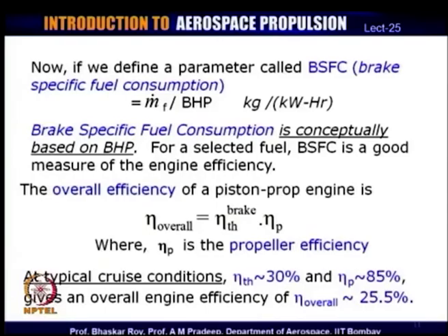And now, we can also look at the overall efficiency of the piston and propeller combined, and this is often given in terms of the overall efficiency, which is equal to the brake thermal efficiency into eta p, which is the propeller efficiency. Okay. And quite often the propeller efficiency comes out of the propeller understanding, which we will probably do later on in this course.